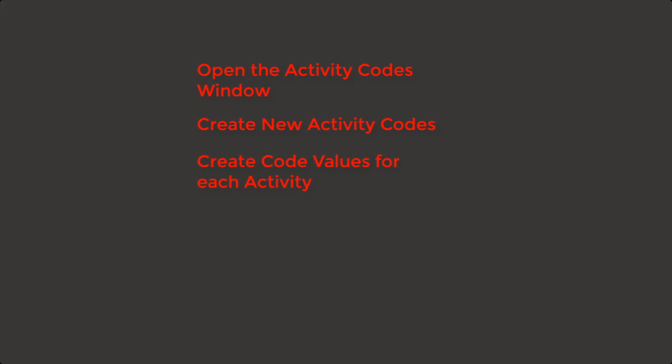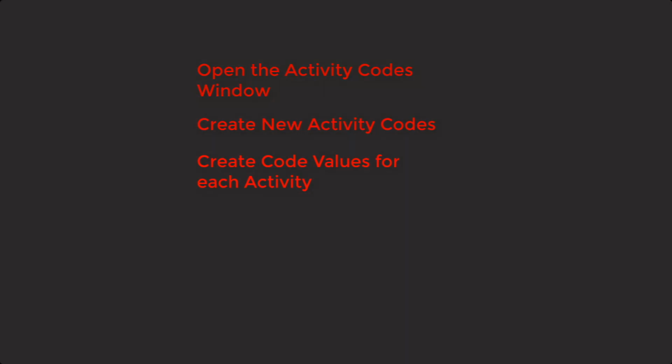To recap, in this lesson you learned how to open the activity codes window, create new activity codes, and create code values for each activity code. In the next lesson, we will assign activity codes to our project.